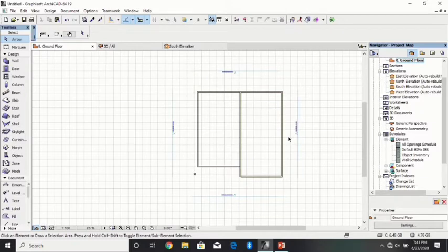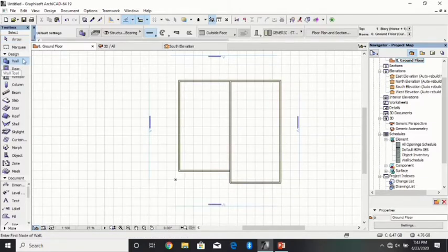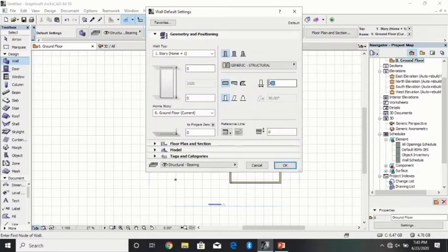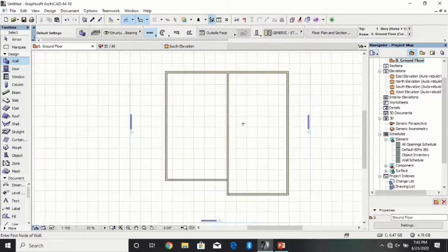We should know that walls have different sizes. So for the interior walls, we're going to have the smaller size, that is 150 millimeters. So we're going to change it to 150 millimeters, and that's what we're going to use. Remember, it's 3100 height. That is standard.